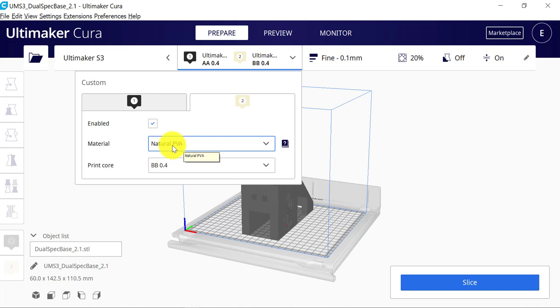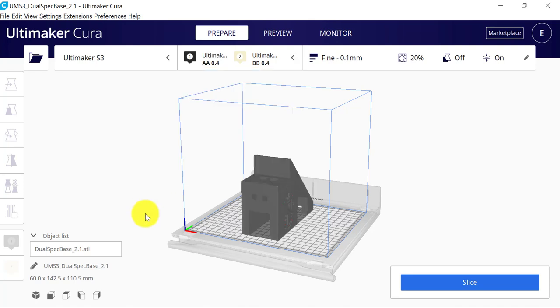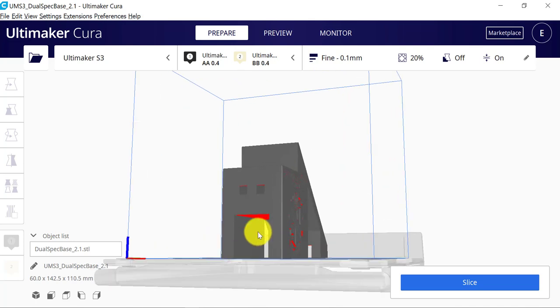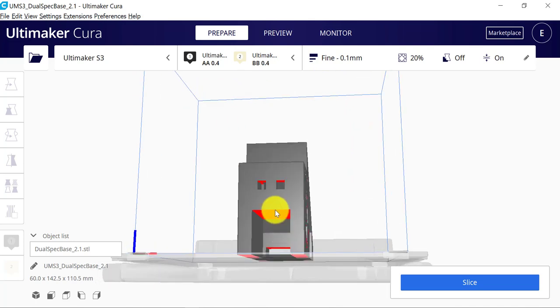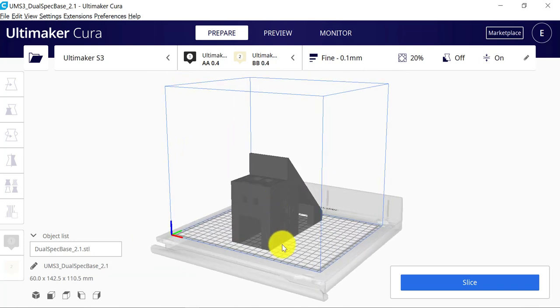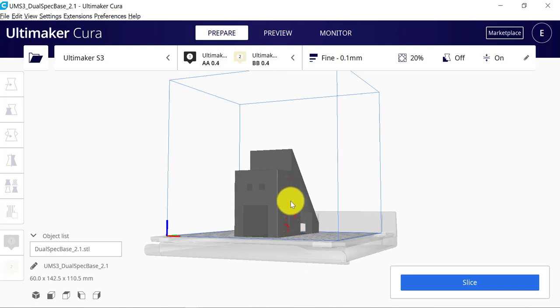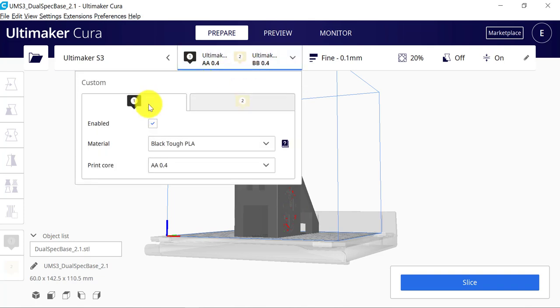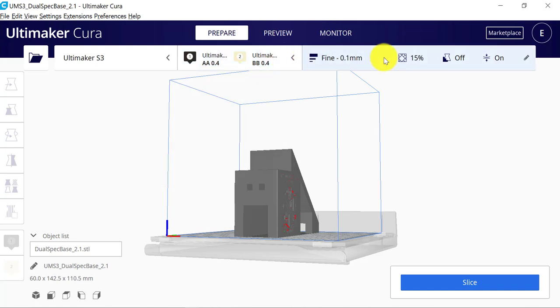This is the stuff that dissolves in water, and the way that this is set up currently, it may not be set up this way when you're using it, is that you could print your PLA, which does not dissolve in water, with PVA as support material. So if you have really large overhang areas that you feel are going to print really poorly, then you could add support to this model, and after you're done, you'll be left with a whole bunch of PVA in certain areas. You can toss the whole model in water and dissolve that away. Okay, so these should automatically load, so you shouldn't have to change these at all, I'm just showing you what they mean. What we do need to change is this function over here.